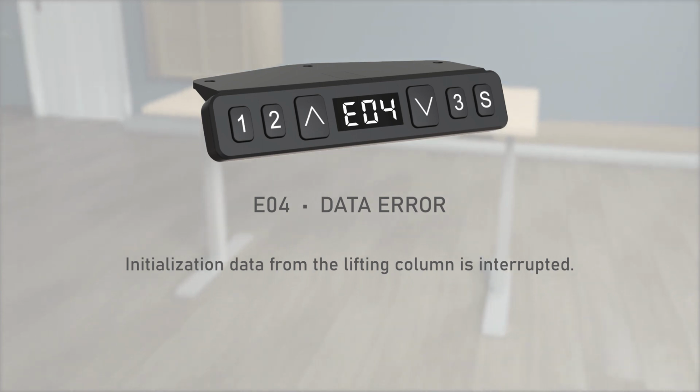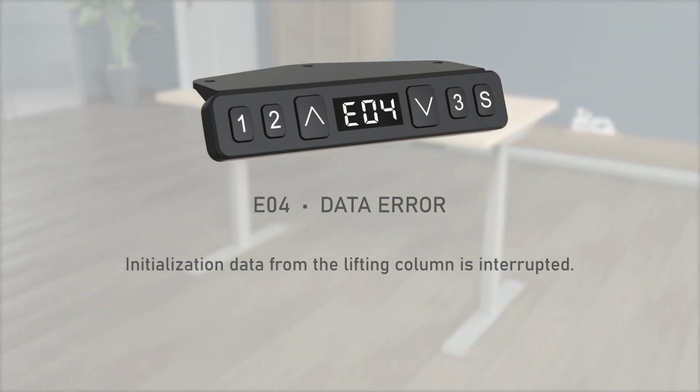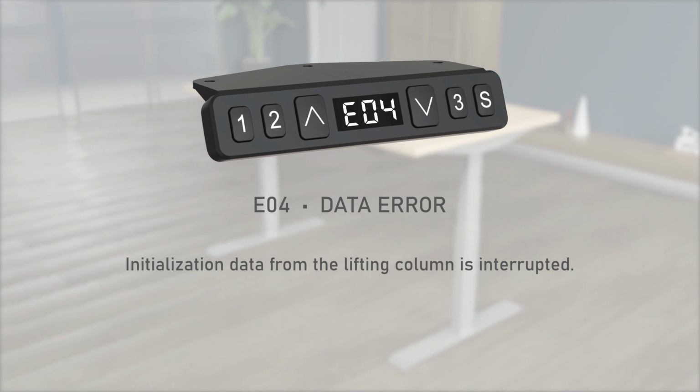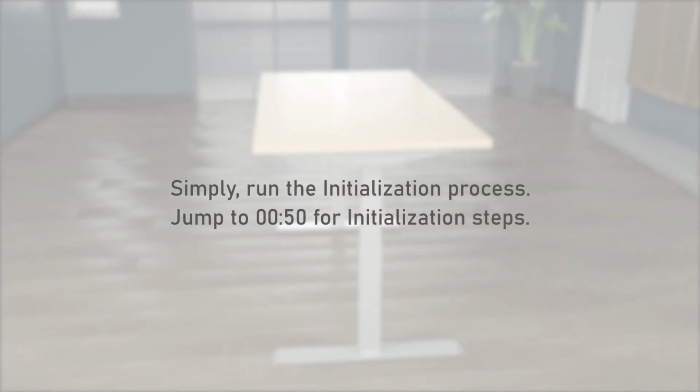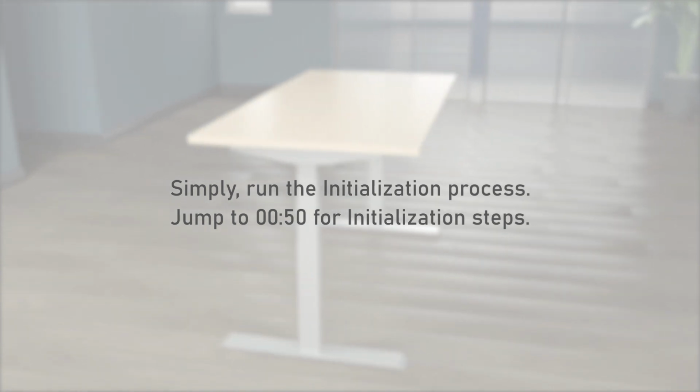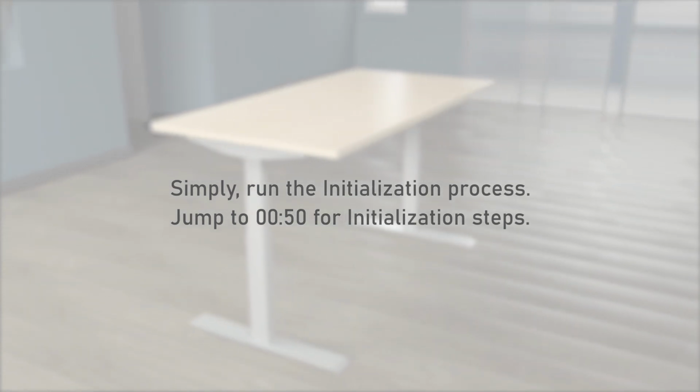E04, data error. Initialization data from the lifting column is interrupted. Simply run the initialization process. Jump to 050 for initialization steps.